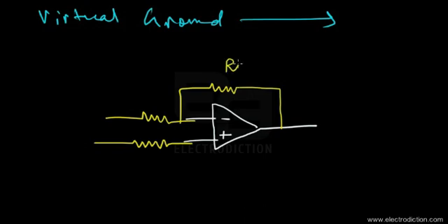You're probably wondering why we're adding this feedback path over here. Well, the feedback path, when added to the op-amp, makes it easier to operate in practical situations. The open loop mode is not so easy to work with. You'll learn about the difference between these two modes. For the present moment, just consider that this circuit is configured to study the op-amp in a very practical way, so we're not using the open loop configuration of the op-amp alone.